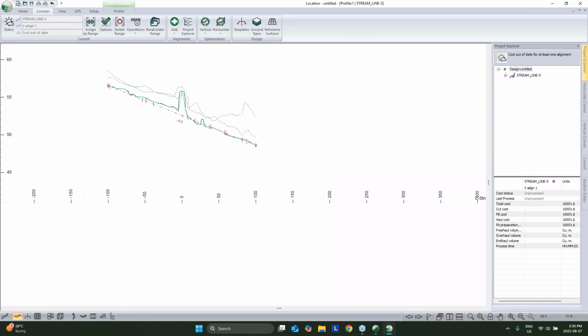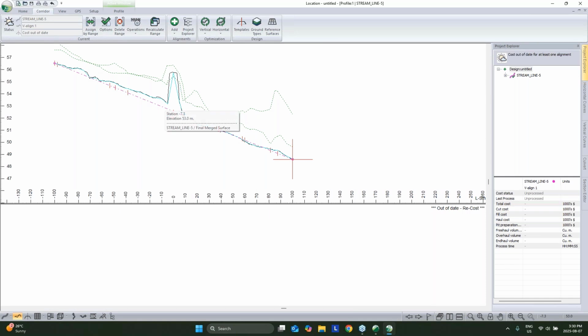Now with this, one thing that stands out to me is that below the existing crossing, our profile's very close to what we'd like, but above it we've got this wedge of material, and I suspect the existing crossing is slowing things down, causing it to drop bed load upstream.